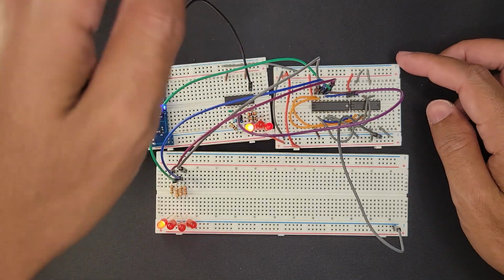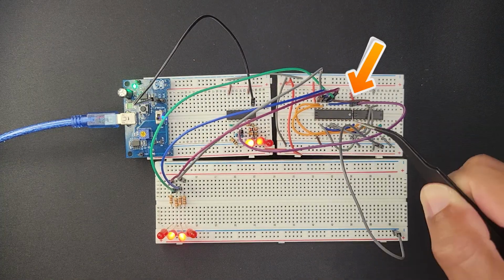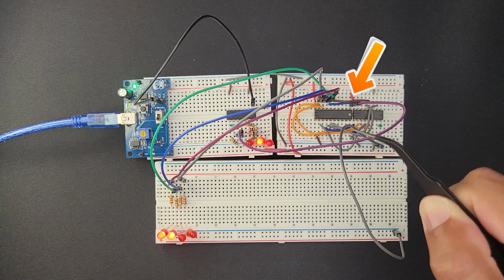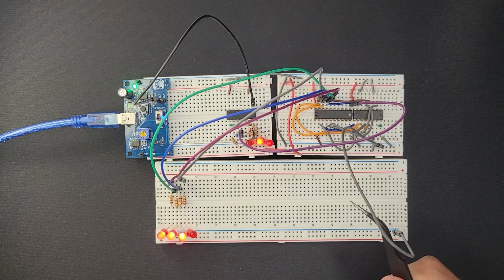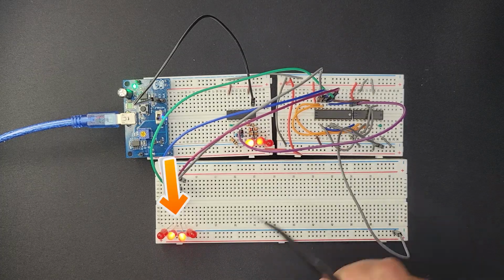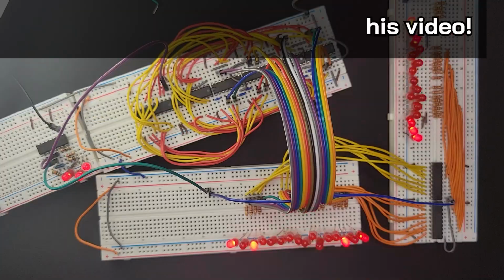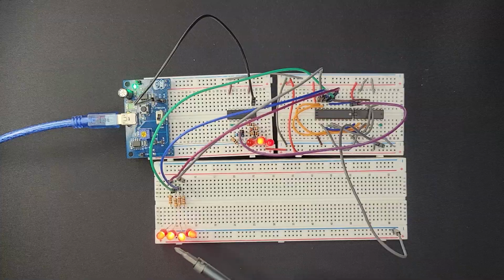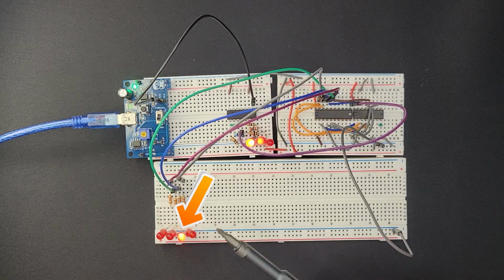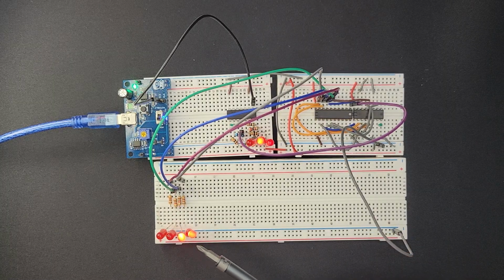So now that the instruction pointer is working, it keeps track of what memory location the CPU is supposed to execute. So what I need to do next is get this instruction pointer value transmitted to a register that can hold it stable for my RAM to access. That's what I'm going to be working on here. And also right now, this is only a 4-bit instruction pointer, but really it's supposed to be 16 bits. Once it's working with the memory address register, I'll update this to 16 bits.